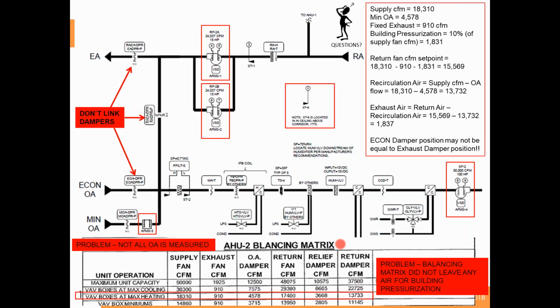And one of the things I highlight here on the left, just a little tip, is very often you will see your dampers linked, your outside damper, your exhaust damper, and your recirc damper all linked as a single output, with, let's say this guy is the inverse of the other two, meaning if this is 10%, this would be 90%. Very common to be done. Occasionally that's not going to work, probably a good percentage of the time.